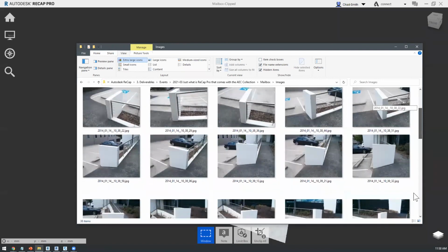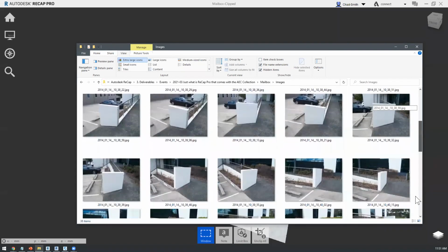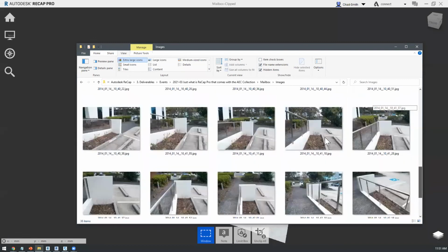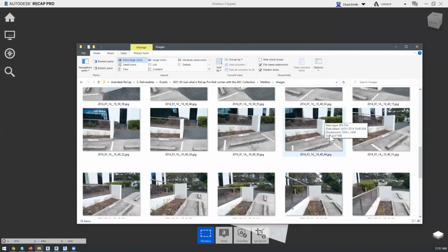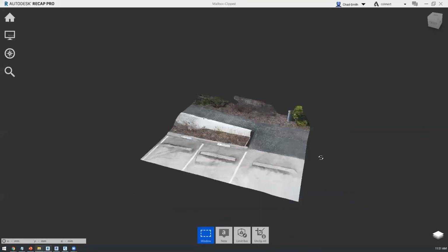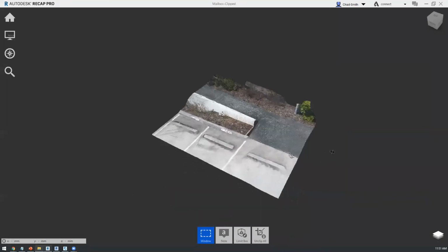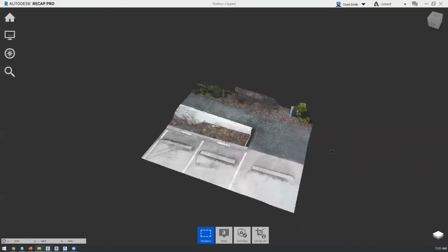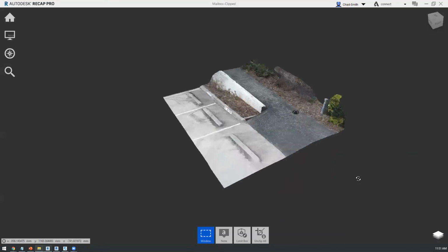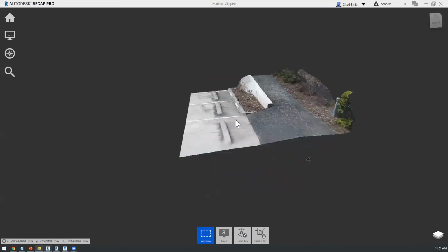Okay, this has 38 odd photos that were taken at ground level, but taken at various heights. So holding the camera up high, bringing it down to about head height, and then maybe going down to around leg height to capture 3 different heights. Again, that was passed through the photogrammetry, that is ReCap Photo, to generate a fairly small, but in this case, reasonably accurate scene.